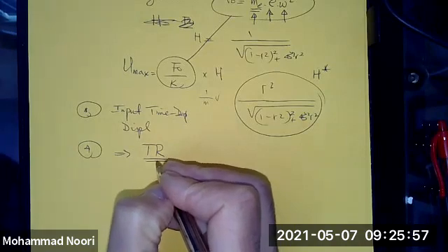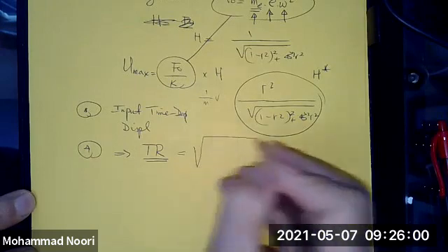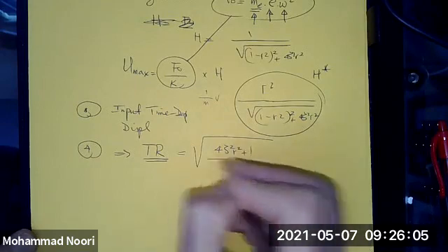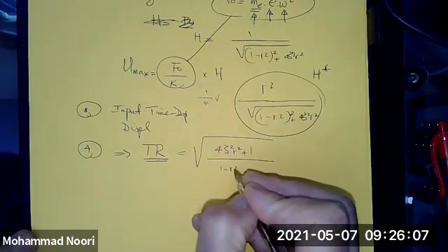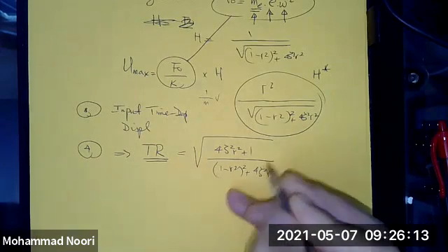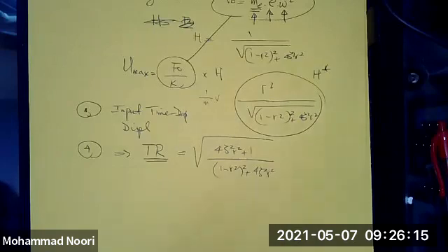We call that the transmissibility ratio, which was this function, okay? 1 minus r squared plus 4 zeta squared. So the transmissibility ratio was the maximum input, no, I'm sorry, the maximum force experienced by the system over the maximum input force, or same thing for the displacement.